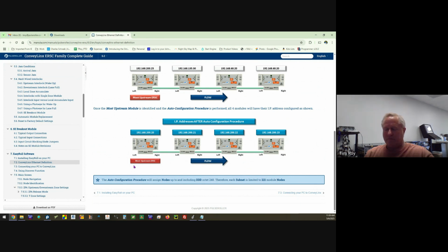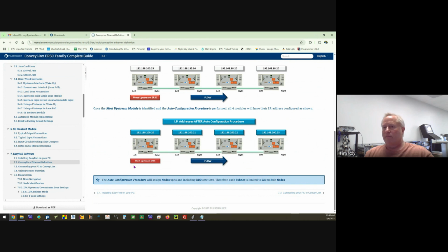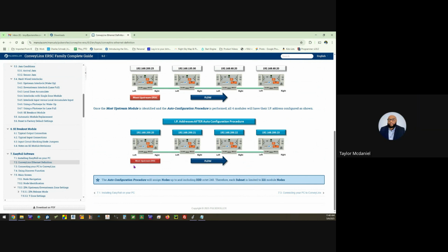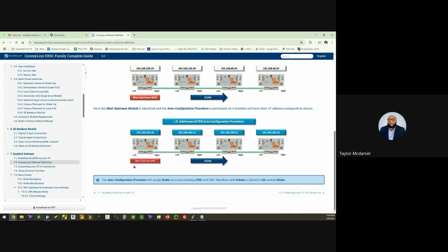And instead of what Nick was mentioning about staggering, for example, you have 50 cards and they all have a 10 millisecond RPI rate. Well, every 10 milliseconds, the processor is going to try to write data to 50 cards. But if you stagger them a little bit, 10, 12, 14, 16, and then do the next set 10, 12, 14, 16, you're still pretty fast on your RPI rates, but you're not going to try to write every card at the same time.